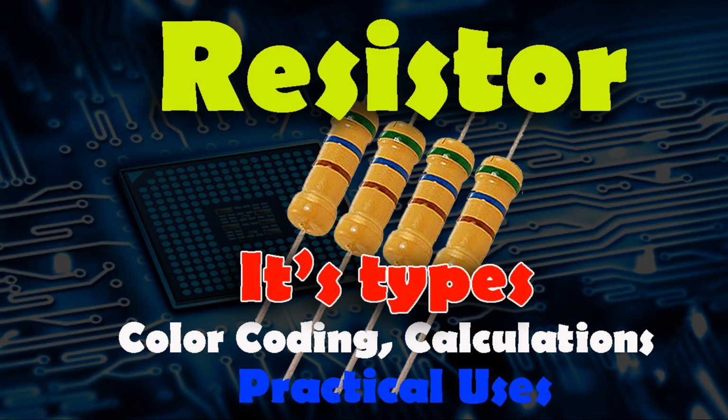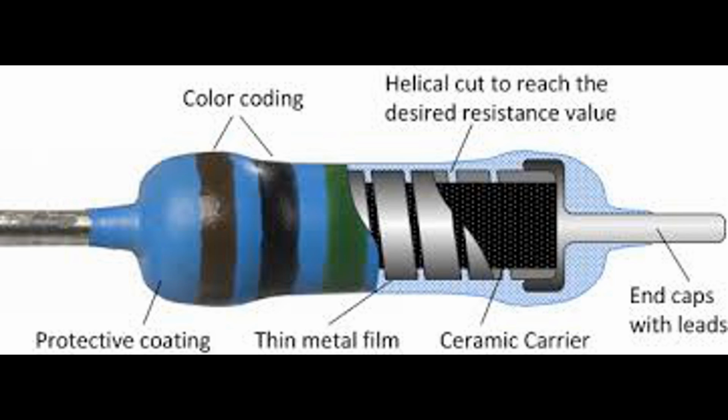Example: a transistor with V_CE = 10 V and I_C = 0.5 A dissipates P = 10 V × 0.5 A = 5 W.